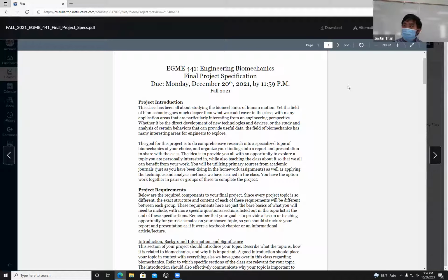But wouldn't the fixed surface be a face on the part? I did it for the wall though, because obviously when you tighten the screws, it will kind of like a strong static friction. So I assume for one of the scenarios I put that as a fix. Oh, okay. I see. On this one, I'm doing it on the ceiling. Ah, it's getting pulled down, so it's only the mounting holes getting all the stress.